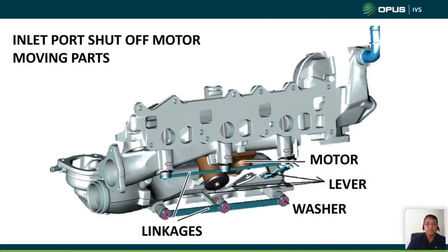That's what is happening, because if that motor is stuck open or stuck closed, all the vents on the intake manifold are not functioning properly. So it's either fully closed or fully open, because the motor seized or because the motor is not working anymore.